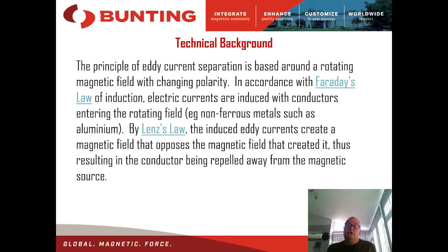We'll now talk a bit about the technical background of eddy current separation. It's basically the principle of putting a conducting particle in a rotating magnetic field that is changing polarity. So in accordance with Faraday's law of induction, electrical currents are induced in a conductor that's entering a rotating magnetic field. By Lenz's law, the induced eddy currents created in that magnetic field oppose the magnetic field that's been created.